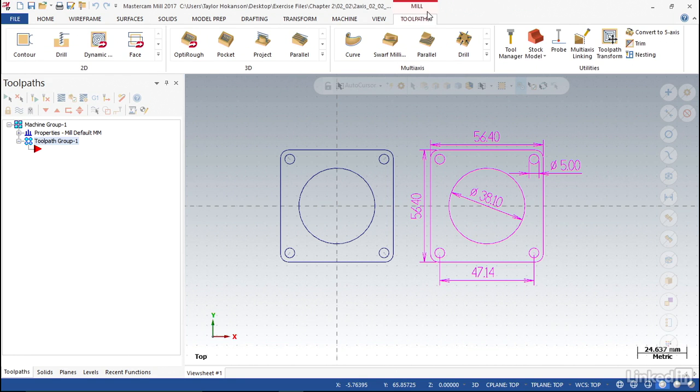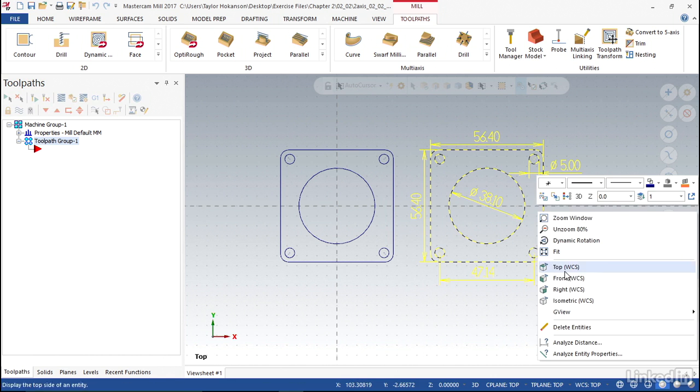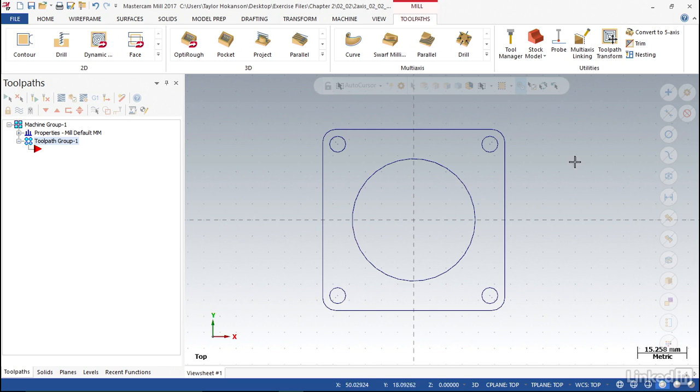That will put a red bar over the top of the Toolpaths tab, and now we expose all the different machining operations or MOPs that can be used with a 3-axis CNC mill. What I can also do at this point before selecting a specific MOP is to establish a stock that we'll be using to carve away from. I should also take the opportunity to delete this test piece of geometry so that now all I've got in the frame is the material I'd like to cut.